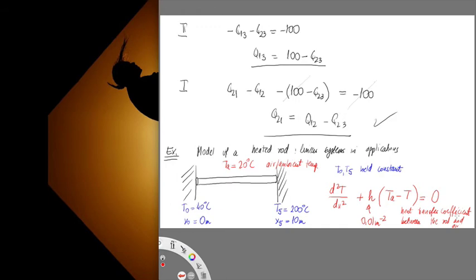It depends on the material that the rod is made of and the air itself. And I'm going to change faster if I have a larger difference between the temperature at every point and ambient temperature. That's what it's saying. So I'm going to cool faster if I have a larger gradient in temperature.